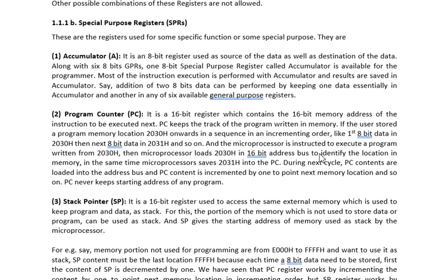Addresses are from 0000 to FFFF. 0000H means 16 bit, 16 lines are there. So this is the address, and we are saying it is an address bus of 16 bit size. So, a 16 bit address bus. This is used to identify a particular memory location in a memory.